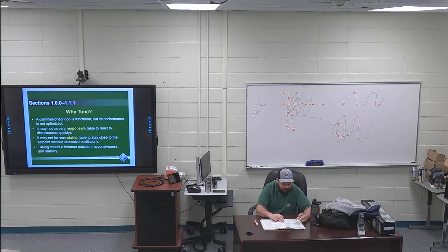Second to last paragraph in section 121 on the right hand side, so second to last paragraph before 122, first sentence is highlighted. It is important to note that with proportional controllers, it's typically necessary to make a small adjustment manually to bring the control variable to the set point on initial startup.